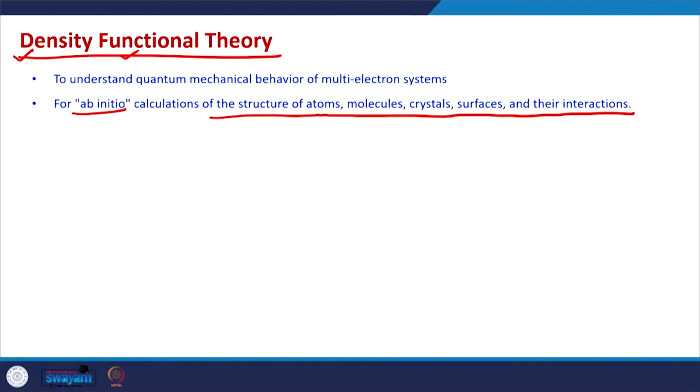Because in our previous discussion, what we have assumed is that we know what is the band structure of the device, what is the band structure of the channel, and from that we can calculate the density of states. From there we can calculate the modes, we can calculate the current, we can calculate almost all the electronic properties, electronic characteristics of the device.